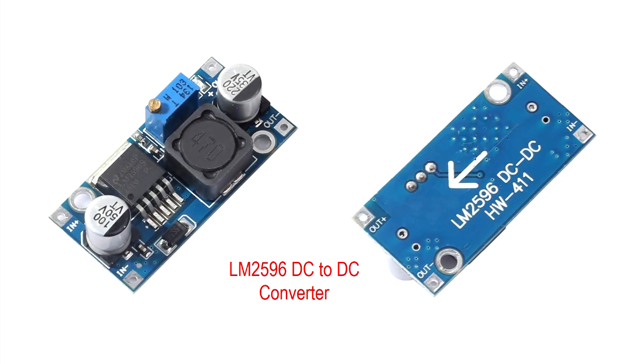The device you require is called the LM2596 buck converter. This is a nicely designed module and is widely available. It is used both by hobbyists and developers as a standard low-voltage converter. It effectively works similarly to the 12 to 6-volt converter for the bell, except these are adjustable and intended for low-current purposes. The best part is that they have become so popular that they are actually sold in packs of 10 for about $20. And yes, it is available on Amazon.